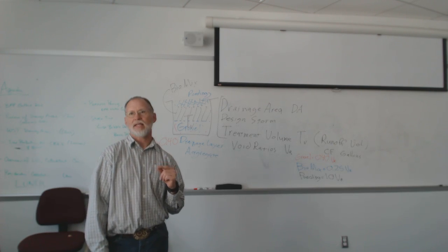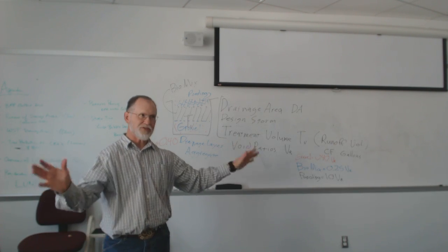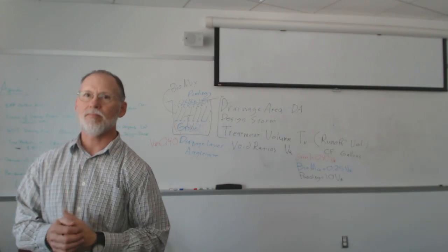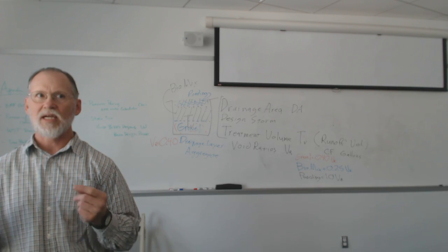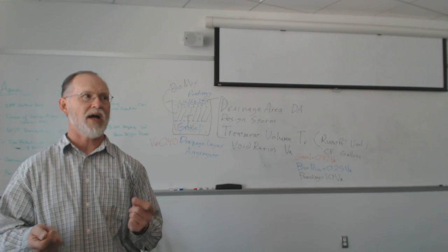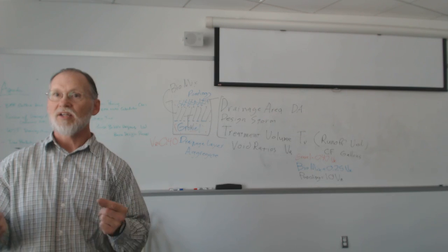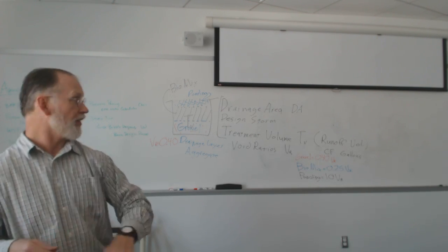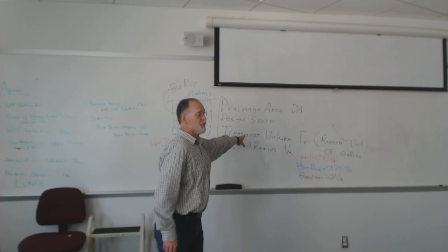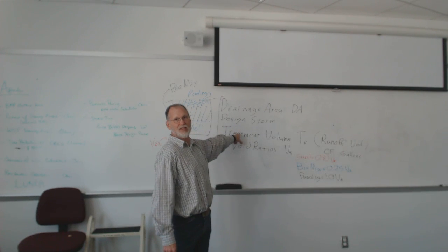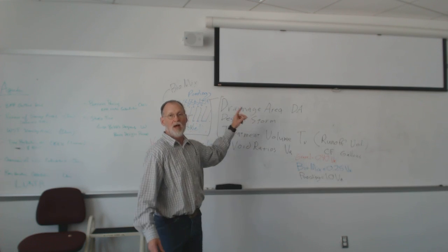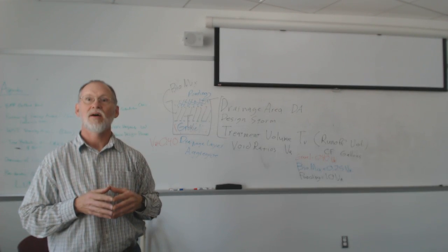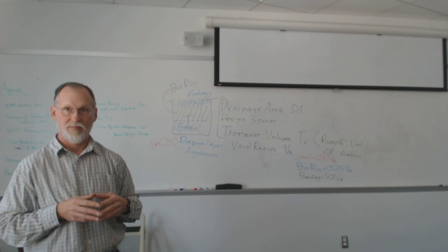Pretty much every LID feature or best management practice I've seen, again, we use different names for the same thing, the 10-year storm is typically required to make sure that much flow can go through your BMP, but that is not your treatment volume. I've never seen anywhere that's treating the 10-year storm. So there are two different things. It's saying you have to design it so that the 10-year storm won't wash it out.